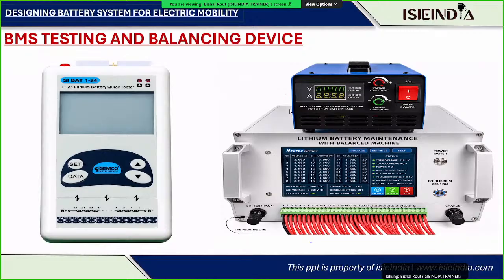Once we connect the voltage sensing wires to the particular pack, we have to test whether the wires are properly connected or not. If the voltage sensing wire has been connected incorrectly, your BMS will not work. At the output, you will not get any kind of value.